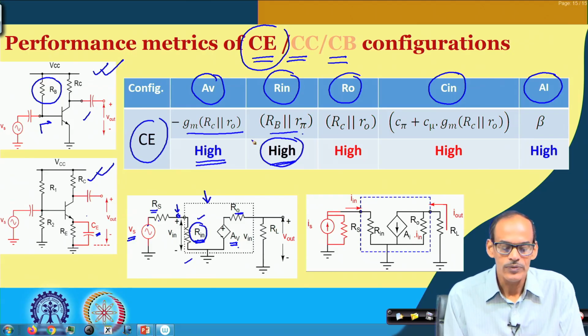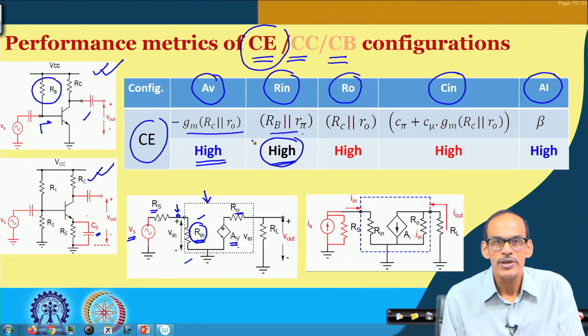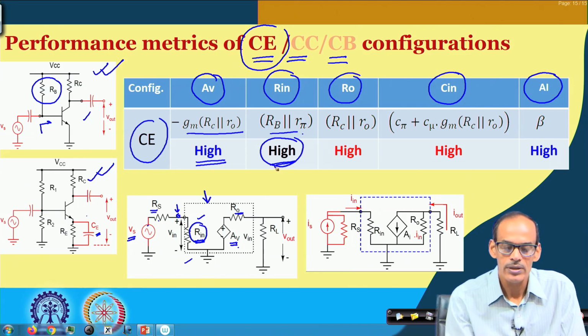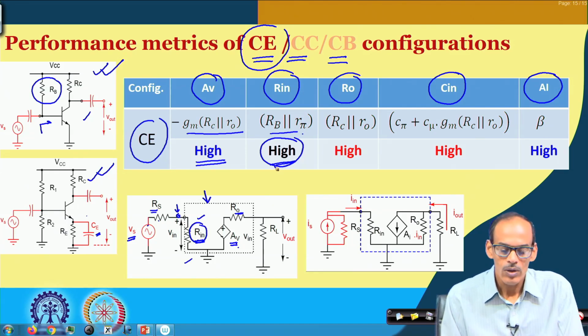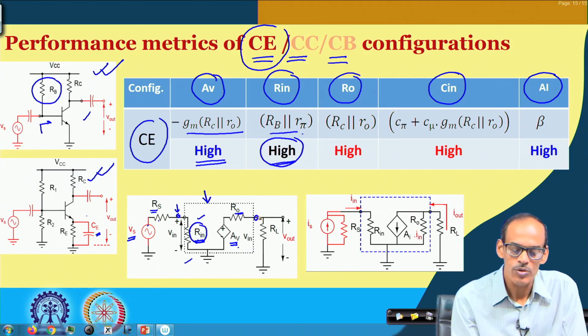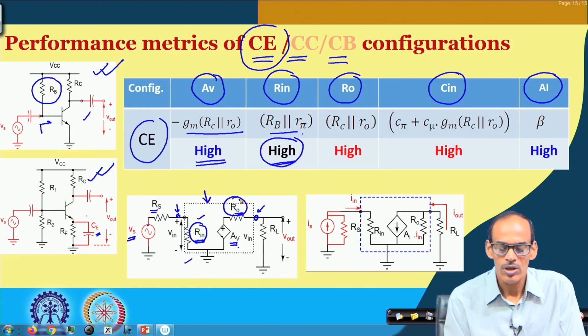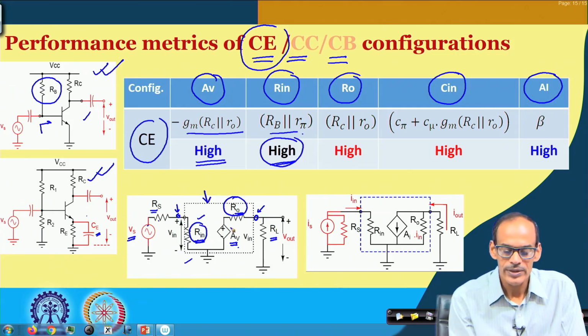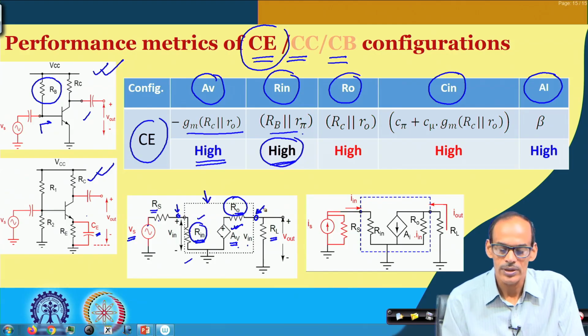So, in case we have some value and we want to further improve this amplifier in terms of input resistance, which means we like to increase the R in further. On the other hand, the signal coming at the output port is voltage, and if the output impedance here is smaller, then in presence of the load resistance, we can say that the internally developed voltage, which is A V times V in, will primarily arrive entirely there.